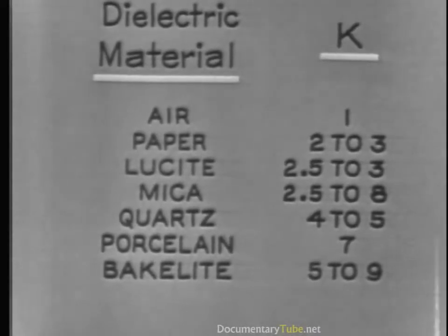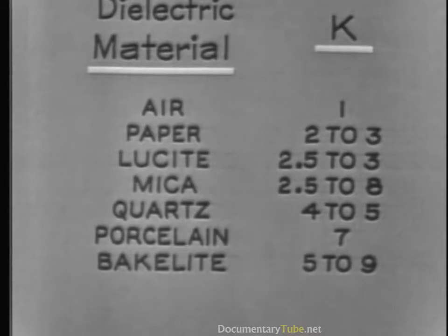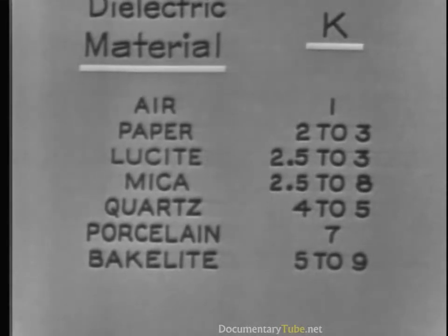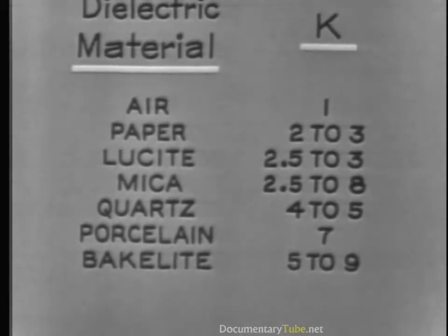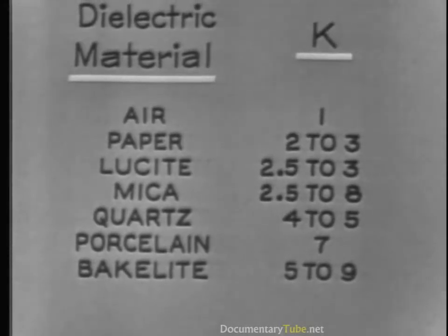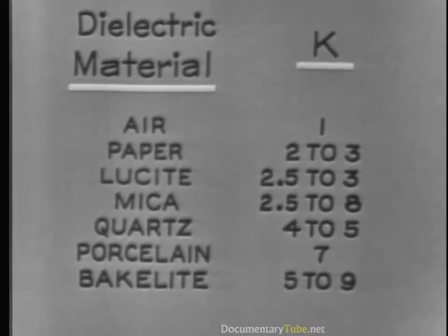Now, I'm sure that plate area and distance between plates requires no further explanation. However, I'll give you a better understanding of what is meant by dielectric K. It all starts with air as the standard. Air is given a K value of 1 and is considered the poorest dielectric in use. Other materials that are used for dielectrics cause an increase in the K rating. The higher the K, the better the material insulates and the higher the capacitance.